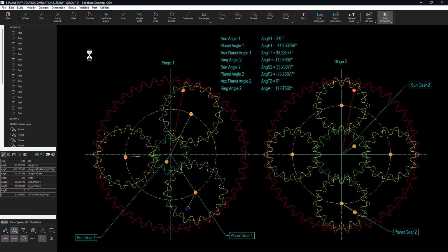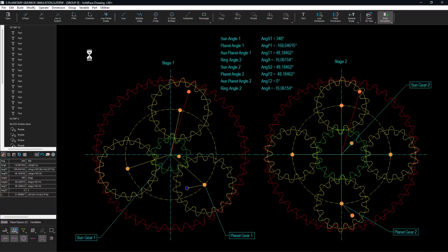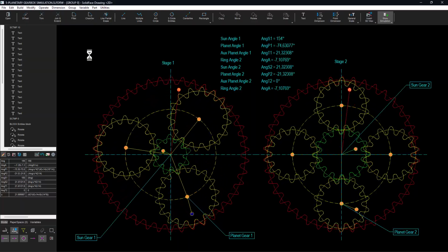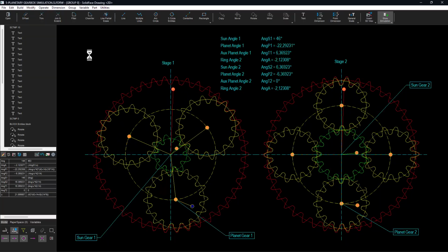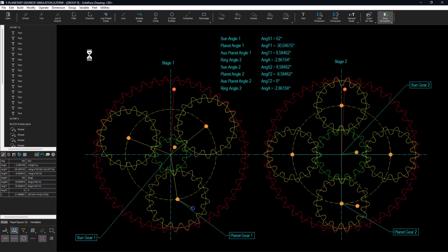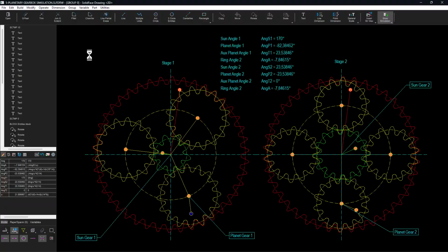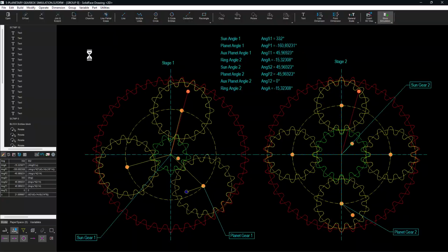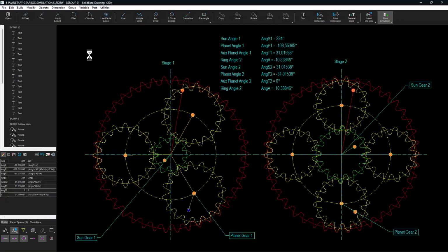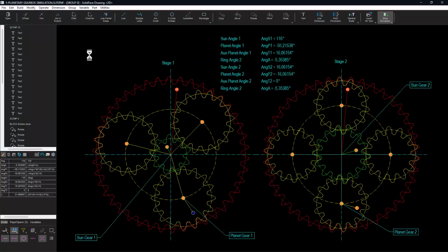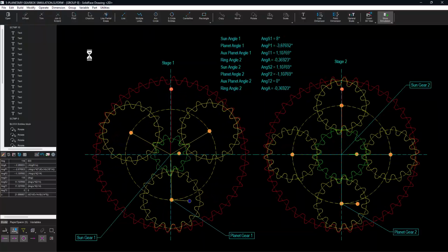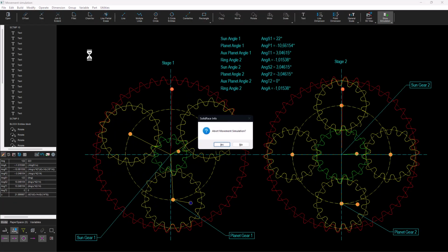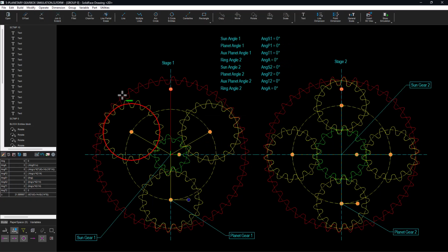In this example, we will show the technique that engineer Norberto Mazzo, a renowned expert in this area, uses to graphically test a gear calculation before designing a physical prototype. To calculate each tooth of the planetary system, he uses an application developed by him called ProGear, which calculates the graphic contour or sequence of points of the gear tooth contour according to the speed, torque, reduction, etc. conditions of the planetary system. This sequence of tooth points is imported into SolidFace using a very simple import function called CADIN import file.